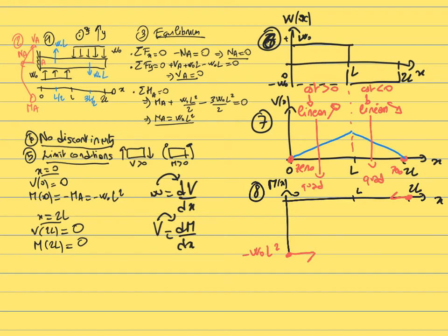It's going to give us the evolution of M. In this case, the internal shear is always positive, which means that M will always be a function that is increasing with increasing x. So now we have everything we need. We know that M is a quadratic function. We know that it starts with a horizontal asymptote.